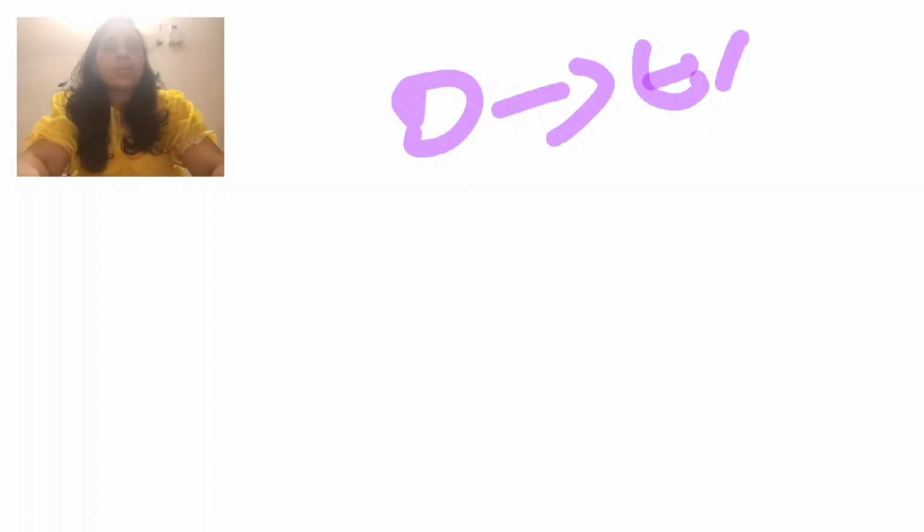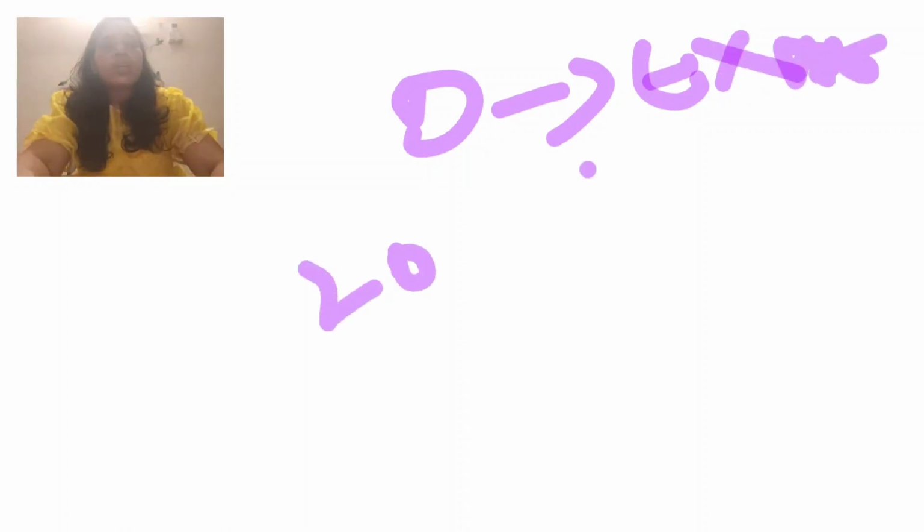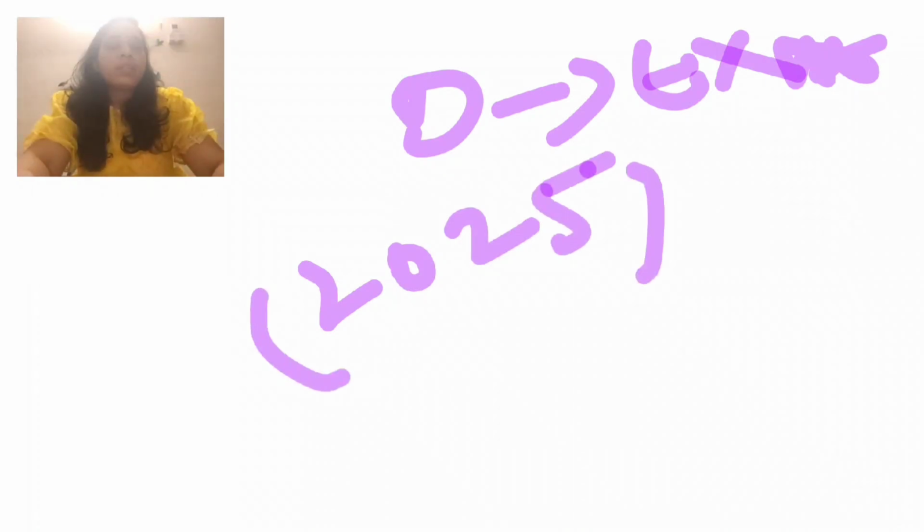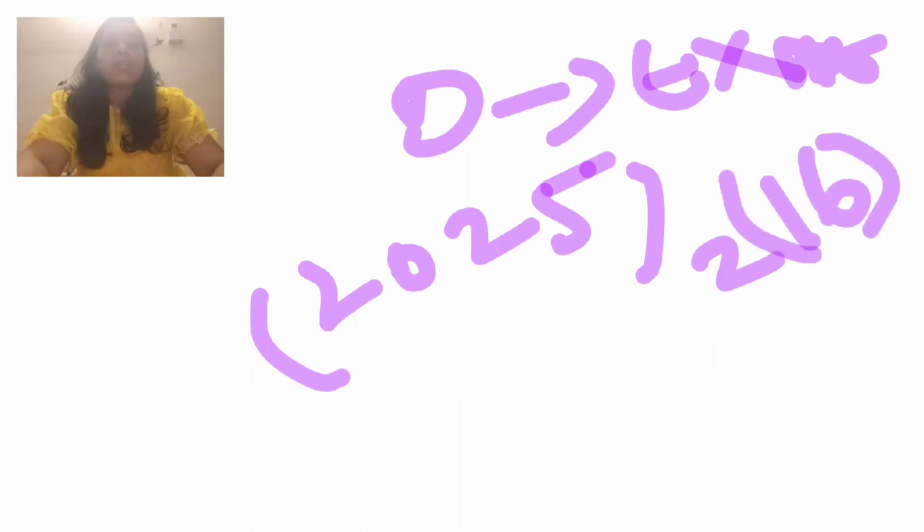Here you can see, we can now write the decimal value expanded in this form. So 2025, how can we do this? Here, for binary, the base or radix value is 2. If it is hexadecimal, we use 16, the radix value is 16. Okay, so now 2025, this is your decimal value, so the radix base is 10.